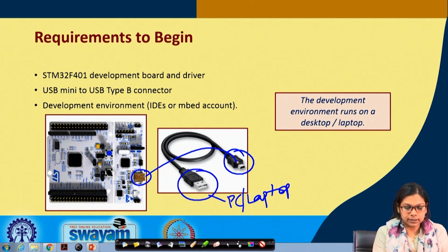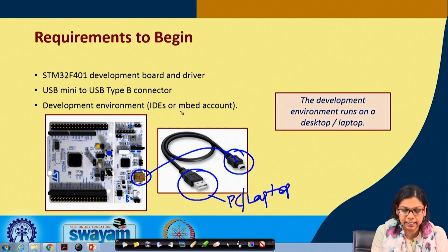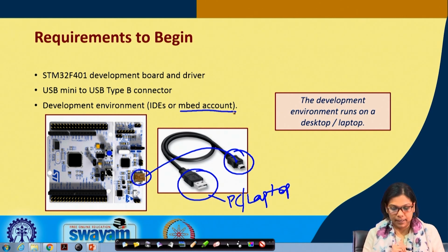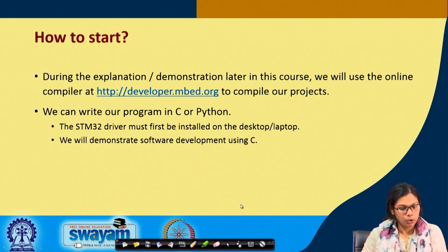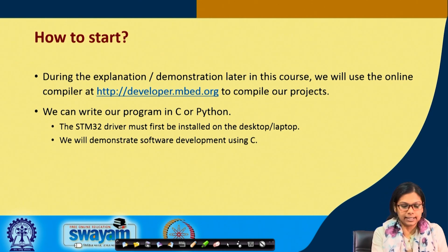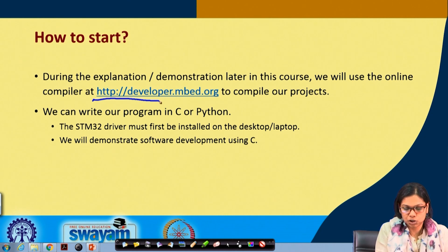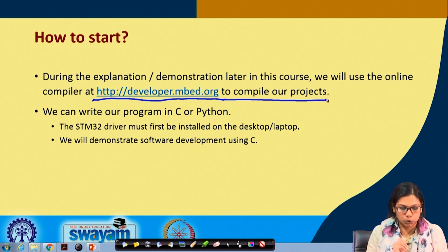As I said, for the development environment, in this case we will be using an online compiler, that is Mbed. So, you need to create an account in Mbed. How to start? During the demonstration later in this course, we will use this online compiler, which is present at http://developer.mbed.org, to compile our projects.